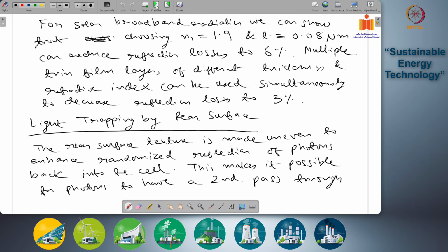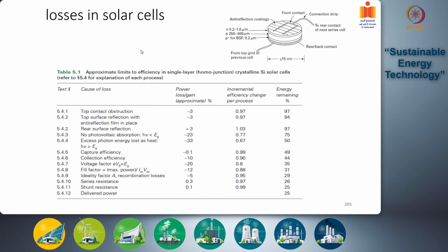If you look now at the design of your solar cell, you can see why you have N plus and P plus doping at the various aspects. So why you have a P plus system, and there will also be an N plus plus system at the top. Now we looked at, for a silicon semiconductor, how we are preventing losses using various designs. But even then, we are getting around 25% efficiency at the end for an idealized silicon solar cell. Now the question is, there are other types of semiconductor materials as well, and how do they fare compared to silicon?